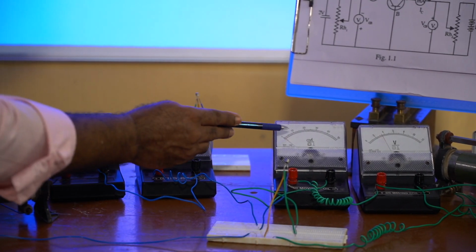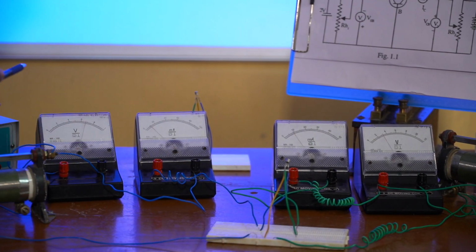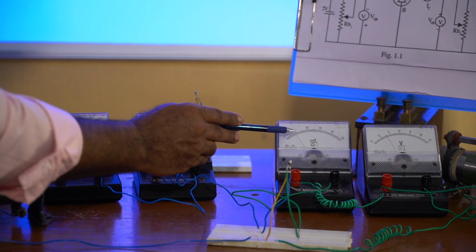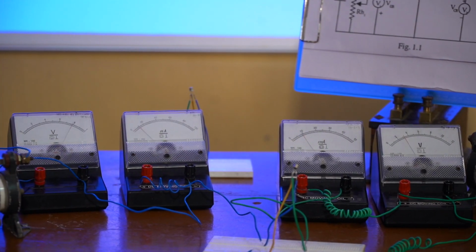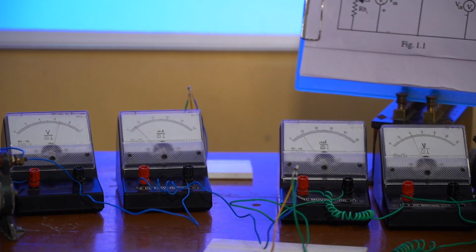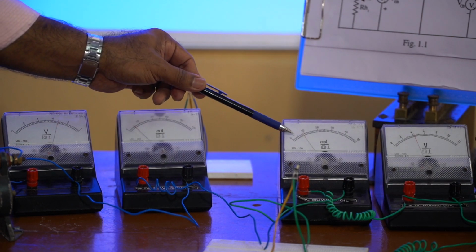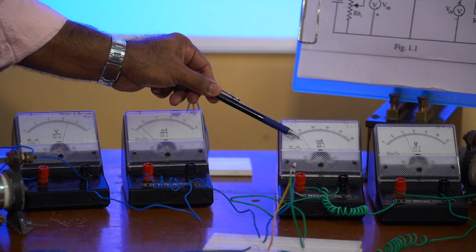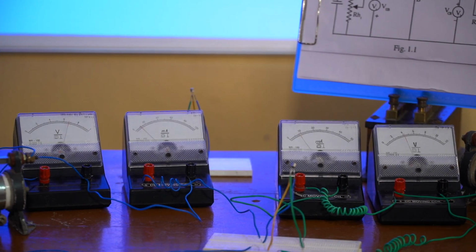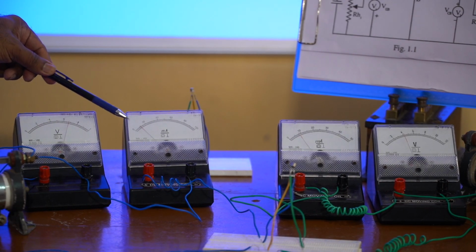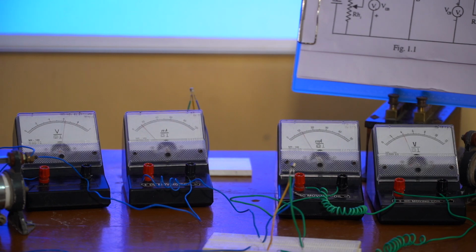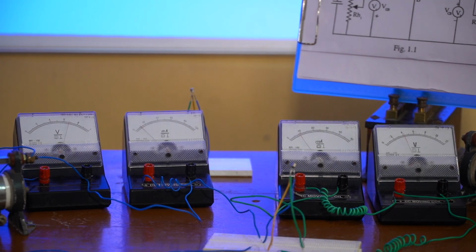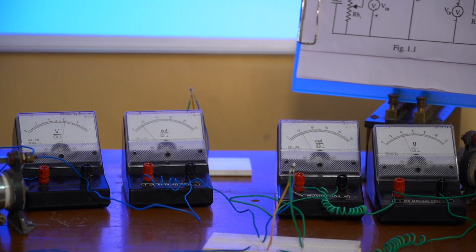Now, IC is remaining almost constant at 10 milliampere. Now, we change to 4 volt. There is no change in the value of IC. So, IC remains a constant at 10 milliampere. So, for a particular value of input current, 10 milliampere, the output voltage VCB is changed. Then initially there is a slight increase in the value of IC, but IC remains a constant at 10 milliampere.